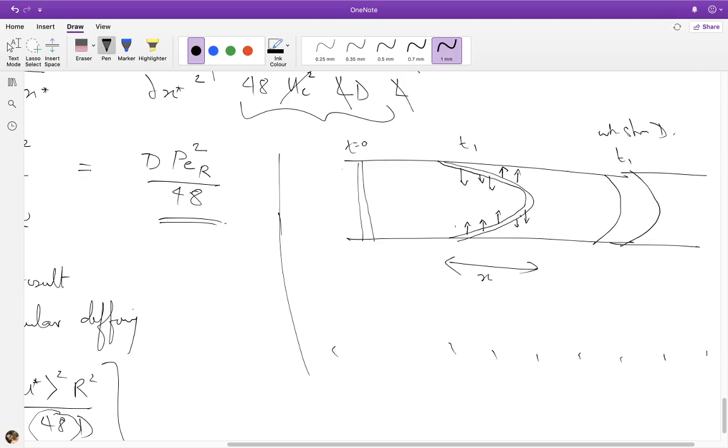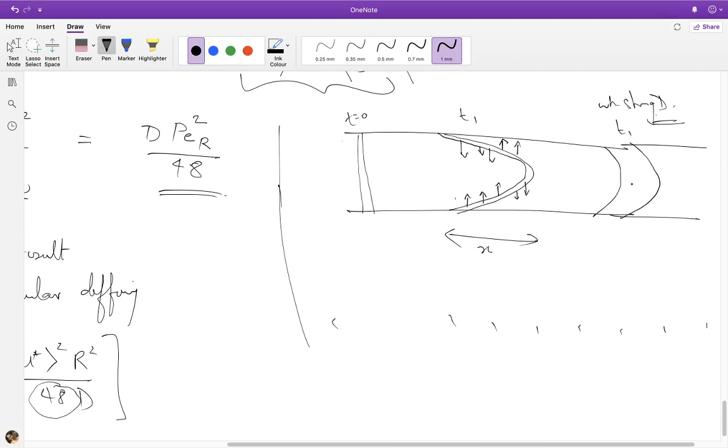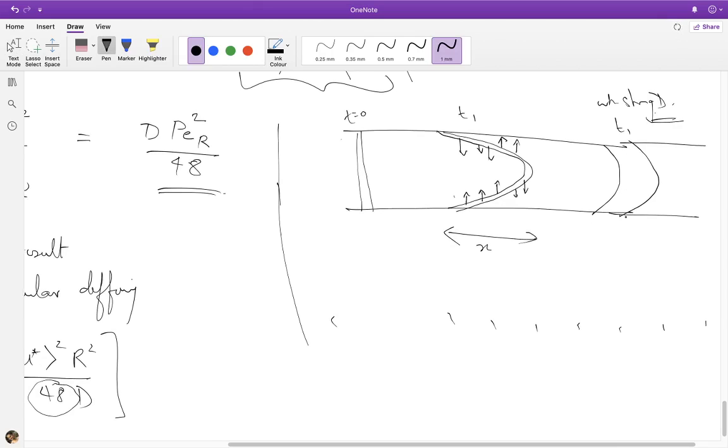Because as it's trying to stretch out, diffusivity prevents it from becoming non-uniform, and if the slug has less non-uniformity in r, the less it will disperse by the convection. So it would look something more like this with strong diffusion. And this is exactly what we did see in the simulations in Fluent.